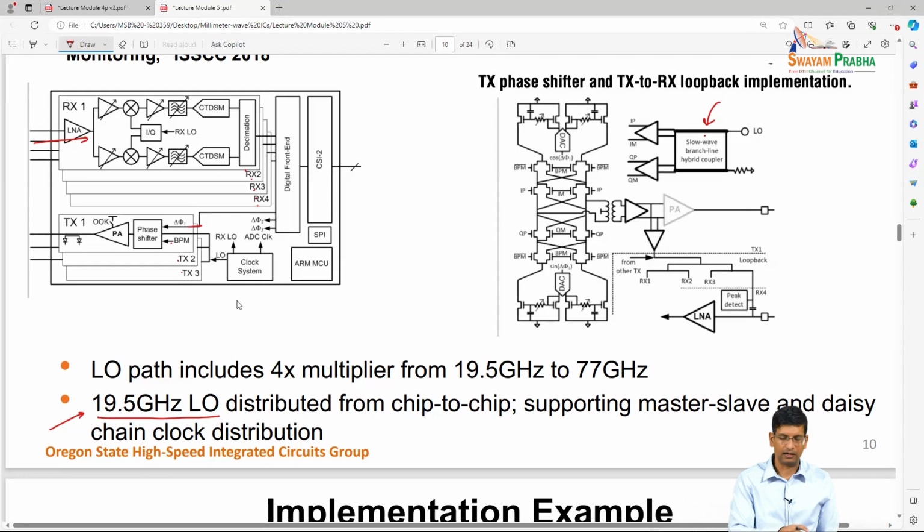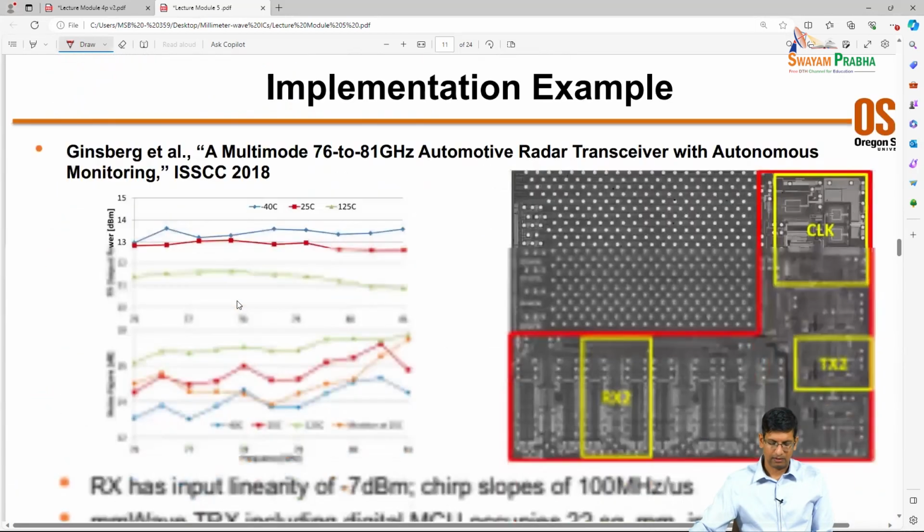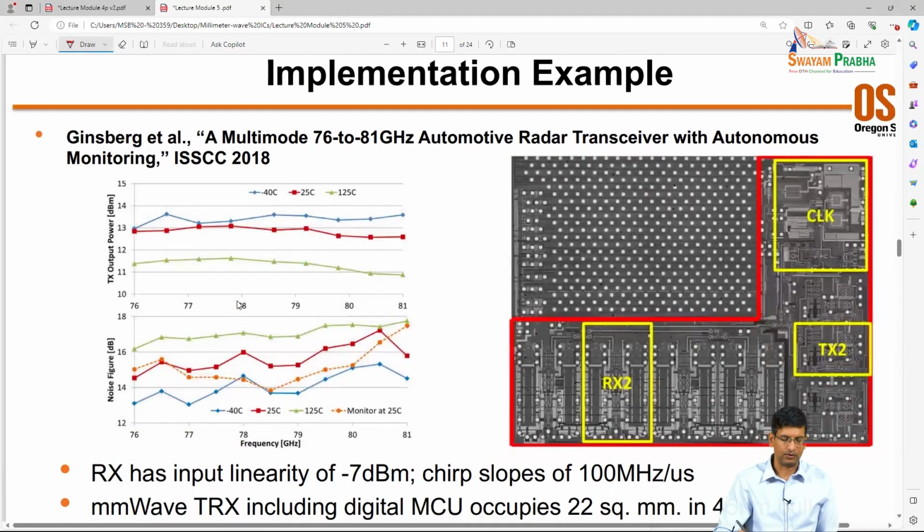And this is again an interesting case study because it includes a lot of the digital signal processing for radar on the IC, along with this 4 RX 3 TX MIMO radar front end effectively. And what we can see here is that the active circuits are occupying a fraction of the area, but the digital part and the digital area consumption is also quite significant.